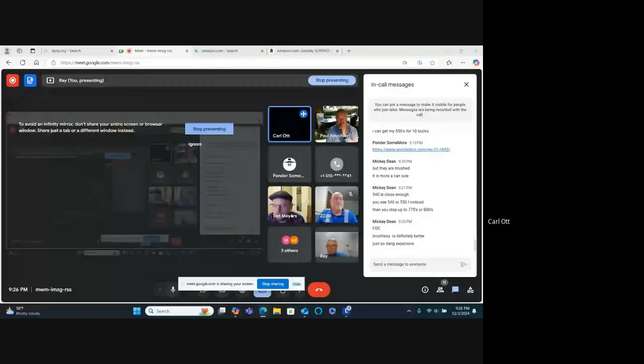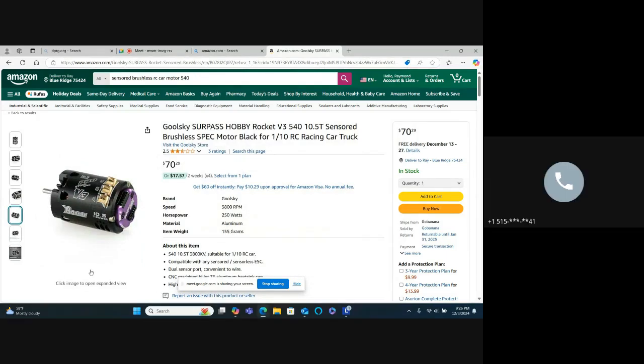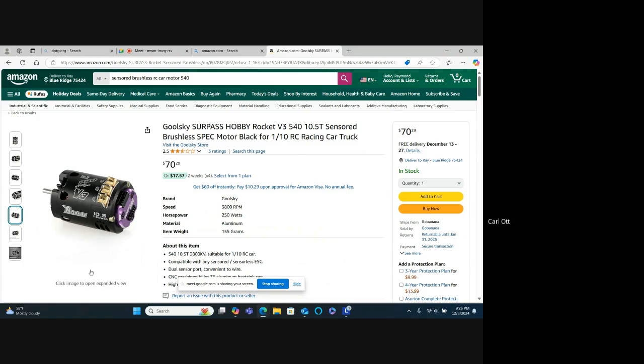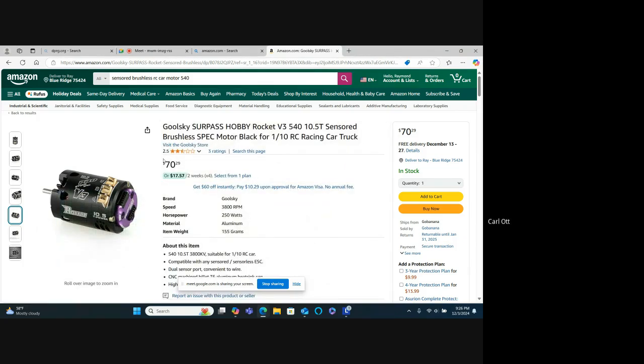Like to be even more challenged with this: if you have two copies of the same model of brushless motor, you can give them the same PWM and the same voltage, and they'll turn at different speeds. Oh, I already figured that one out. So if you try to drive straight, you need to adjust for that without a gyro or a compass. I mean, you need encoders.